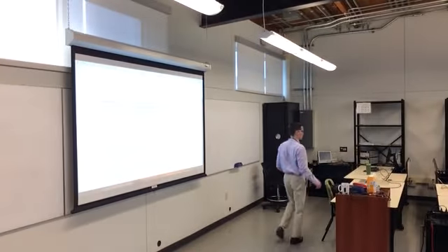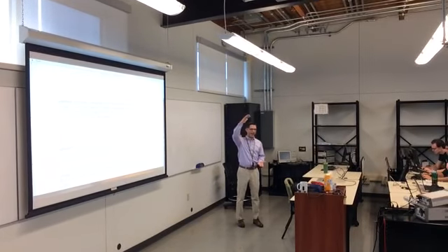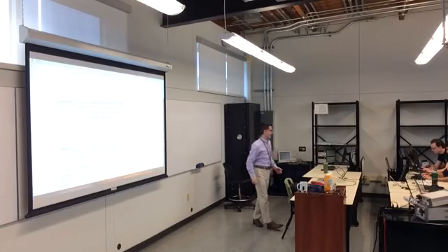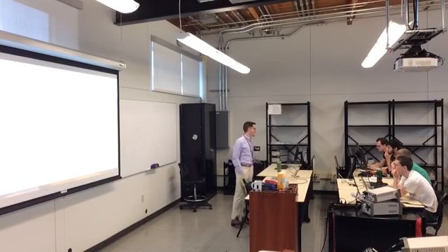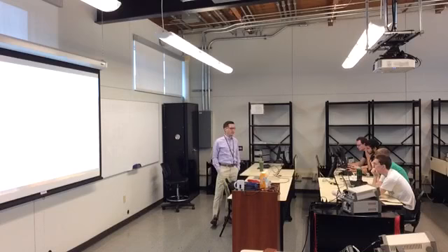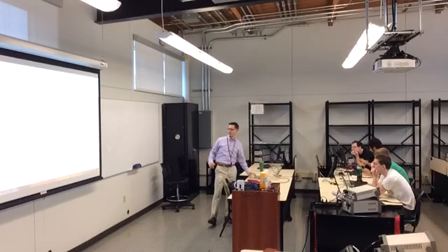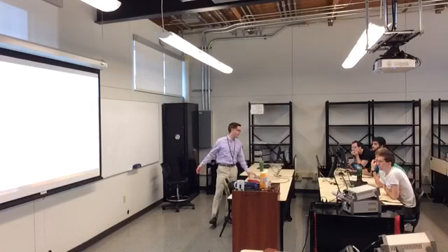Remember, in terms of your memory, the stack grows down as you push functions and variables, and the heap is sort of for your global and static variables. The heap is more important in a dynamic memory allocation system like any other desktop computer, but we do not do dynamic allocation on an embedded system because it introduces non-deterministic behavior. If I'm swapping data structures in and out of memory, am I going to miss something? Am I going to run out of memory? What happens? So you should have found main is located in Flash. It's part of the program, so it should be located inside the Flash memory.